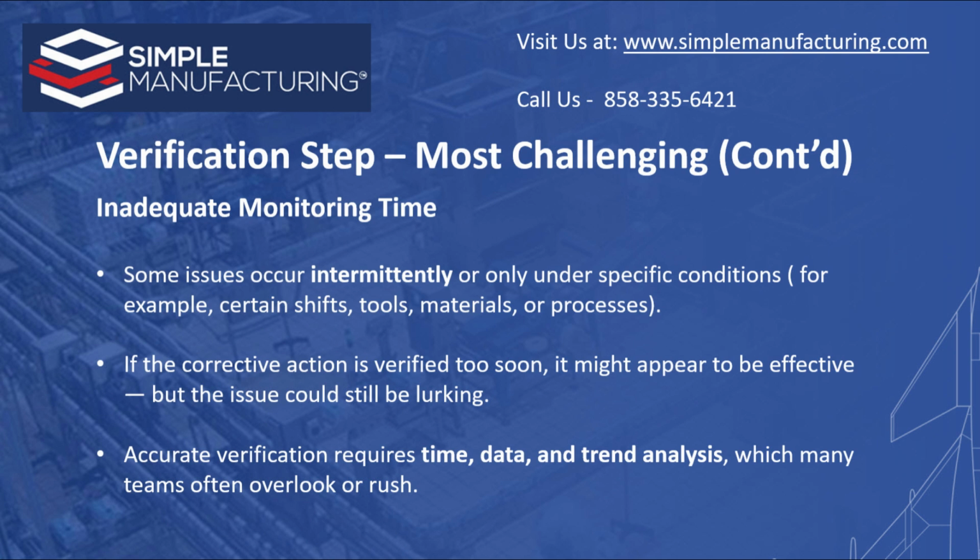Second, inadequate monitoring time. Some issues occur intermittently or only under specific conditions, for example, certain shifts, tools, materials, or processes. If the corrective action is verified too soon, it might appear to be effective, but the issue could still be lurking. Accurate verification requires time, data, and trend analysis, which many teams often overlook or rush.